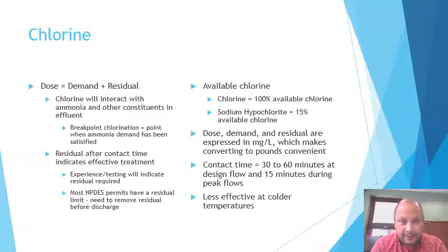So after you've injected chlorine and had it go through the contact process, and most of the time there's going to be a chlorine contact tank with baffles to redirect the flow and get good mixing and adequate treatment time. You can see here on the slide that we're looking for contact time between 30 and 60 minutes at design flow, and at least 15 minutes during peak flows.